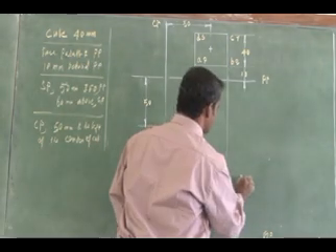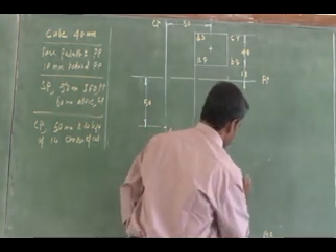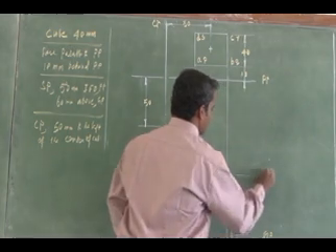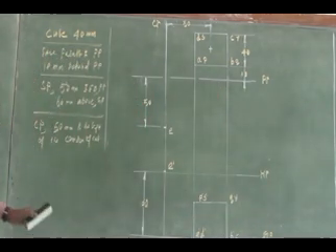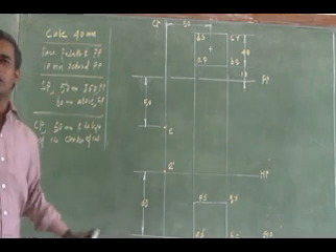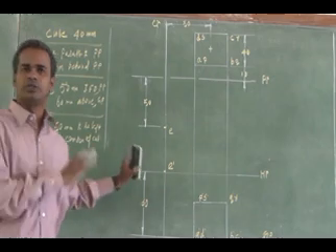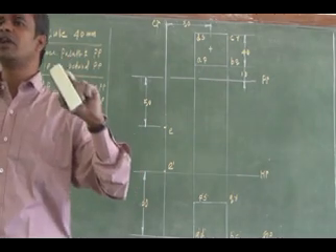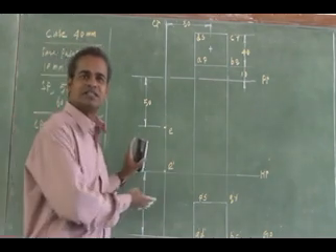This is the location of my horizontal plane. If the problem is given, you try to draw the layout like this at an appropriate location, in 2H pencil. Both your views should be drawn in 2H pencil. Do you have any clarification? Just your work is this.